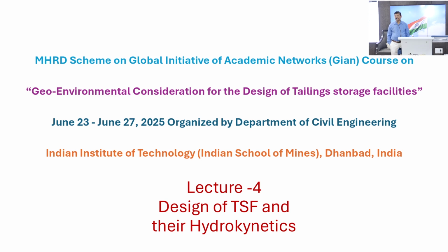And in tailings they are very much related. So you cannot separate them. That's the main concept of tailings compared to the hydro dam, because the seepage is very important in the tailings. That's controlling the stability also.